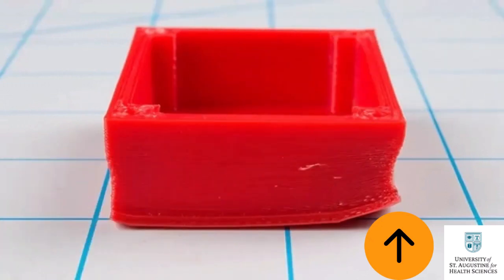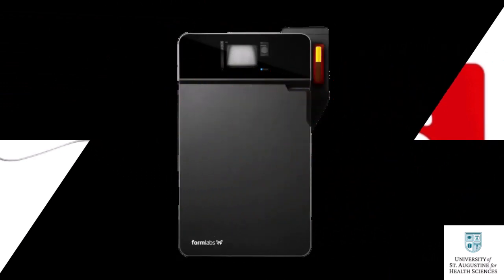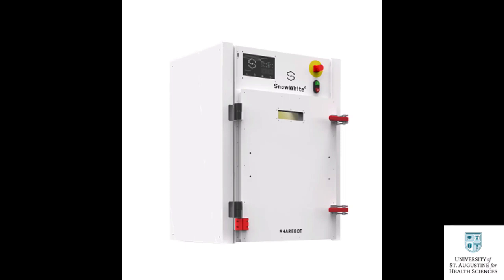SLS printed objects are also prone to shrinkage and warping. SLS 3D printers are more expensive compared to SLA and FDM printers, with a price range of $5,000 to $250,000. Examples of SLS 3D printers are: 1. Formlabs Fuse 1 Plus 30W, 2. Sinterit Lisa Pro, and 3. Sharebot Snow White 2.